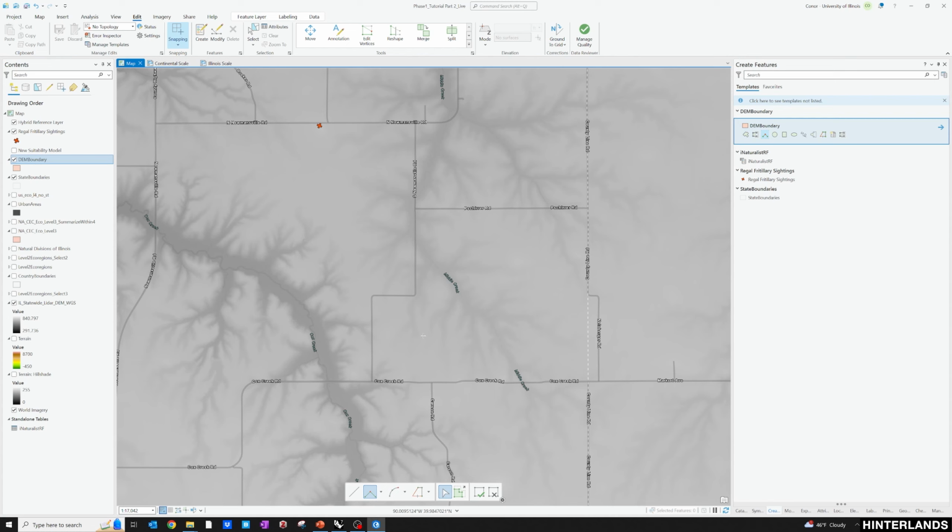And then over here on the drawing, I'm basically going to draw a square. And so we want to create a square that is 150 acres. And so to do that, we need to draw a square that is about 2,556 feet by 2,556 feet. If you have questions about how I calculated that, just drop some questions in the comment section here. But I'm going to go ahead and click once here, maybe here near this creek. And then I'm going to right click.